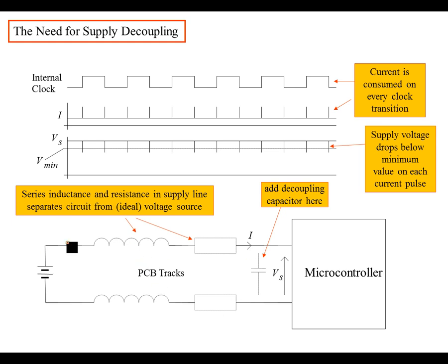Now, because your battery is sometimes located remotely, not directly close to your microprocessor, you have this problem of inductance. Again, the inductance is caused by the loop. You may have a battery here, and wires going like this to your microprocessor. Twisting those wires together will minimize inductance, but it's not going to completely eliminate it, though it will have a huge effect on the value of this inductor. You want this inductance value to be small.